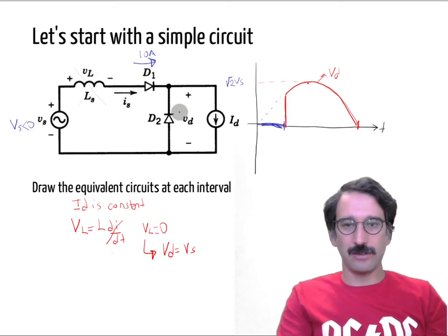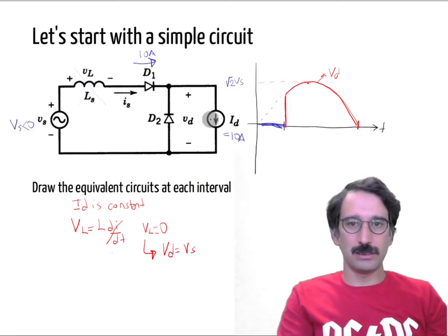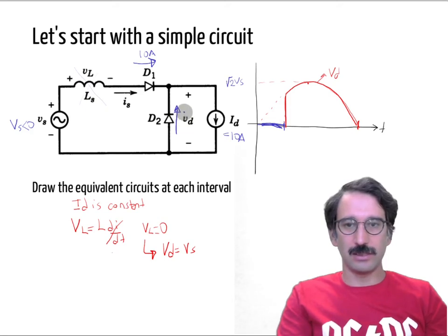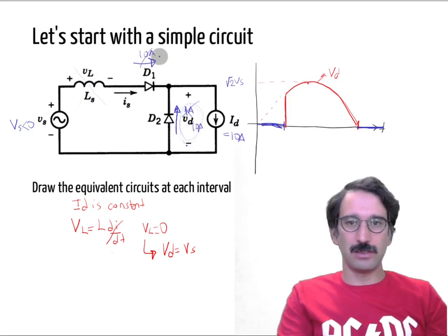So just after a little while, this would like to see 10 amps no matter what, and this will start carrying, let's say, 1 amp, and whenever that starts conduction, our output voltage will be 0 again. It will take 2 amps, 8 amps, 3 amps, 7 amps, whatever, then it will reach 10 amps again, then this will reach 0 amps, then it will get closed. But from the output voltage level, it doesn't really matter.